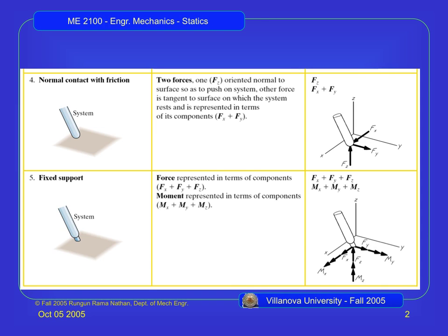Now, this is normal contact with friction, but with 3-dimensional friction. So take a look at it. Fz is the normal force. Fy and Fx are just the friction forces. So on your chair, as soon as you sit on it, besides the fact that it has cross members, you see on the bottom of these chairs? These cross members are preventing these legs from going out, from separating. It's a stable system. If this was not here and you were heavy enough, technically it could separate, right?